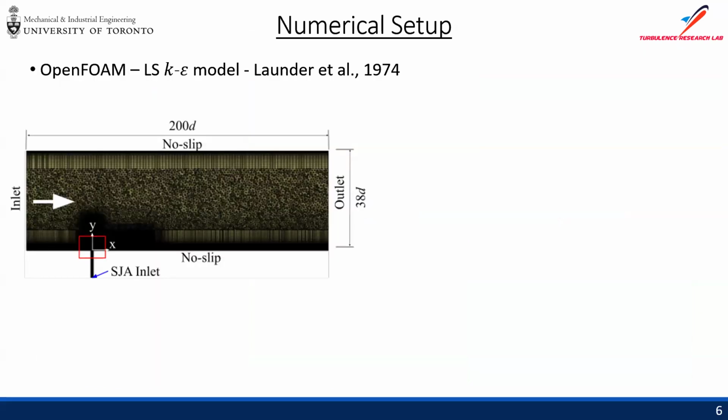So we're going to move on to the numerical side of things. The simulations were conducted in OpenFOAM with the Lam-Bremhorst k-epsilon model. This is based on a standard k-epsilon model, but with damping functions employed, giving us a little bit better results close to the wall.